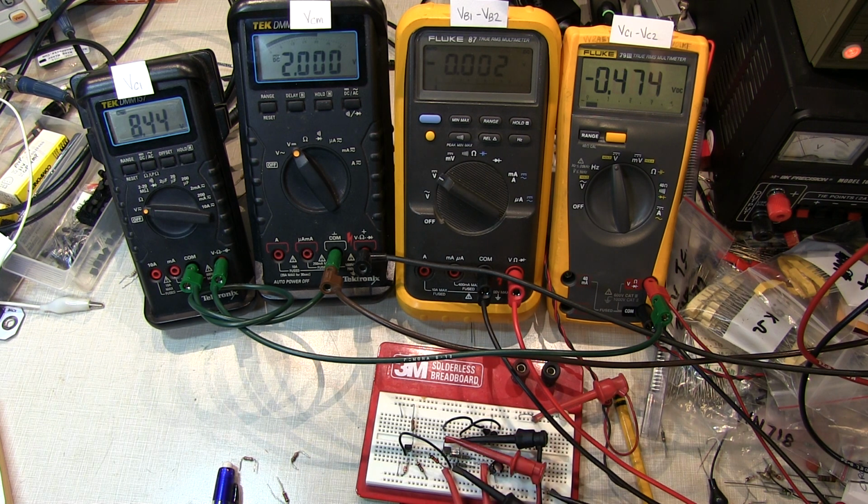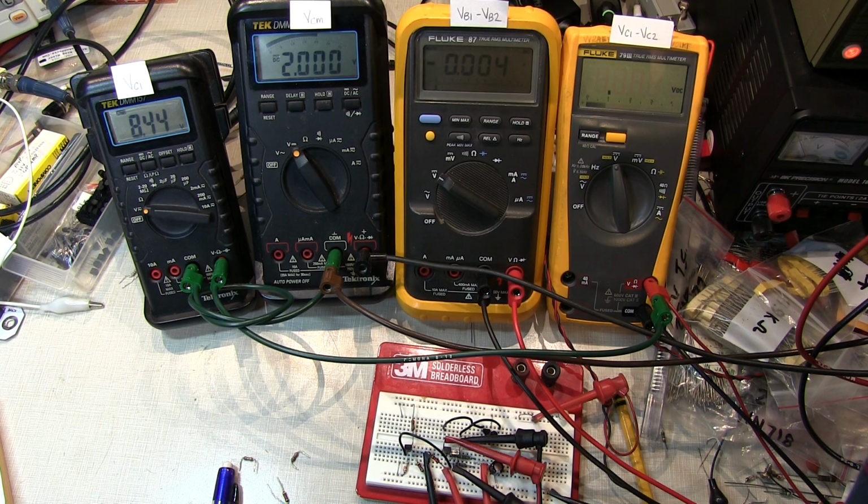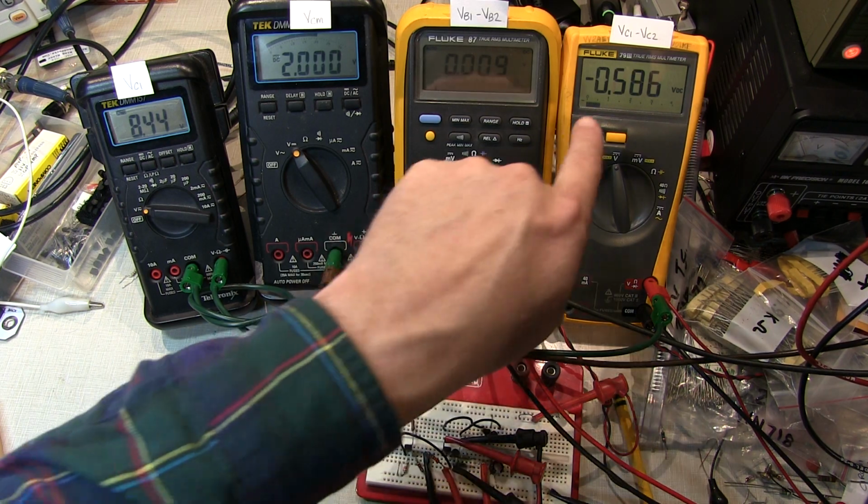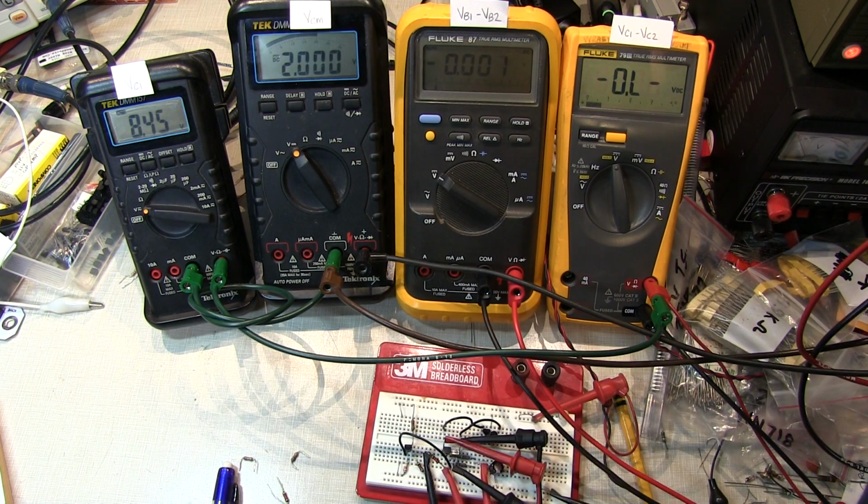In fact, I was trying to adjust the input voltage difference to get the output voltage to sit mid-rail, and I just couldn't do it. The gain is so high that just a few millivolts one way or the other rails the voltage difference one way or the other. This is kind of like the open loop behavior of an op-amp. Without feedback, you're not going to make the output do anything usable, and that would be the same thing in this case here.